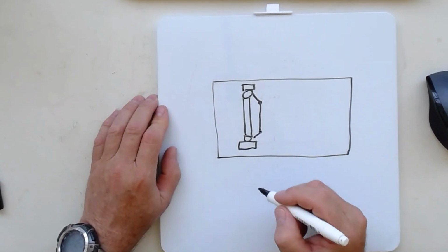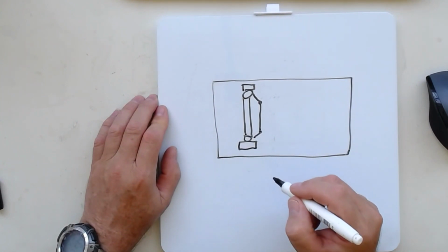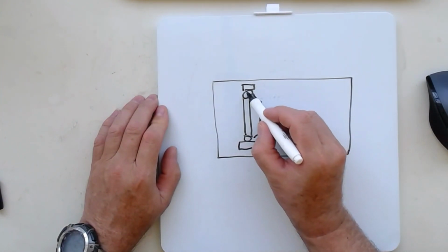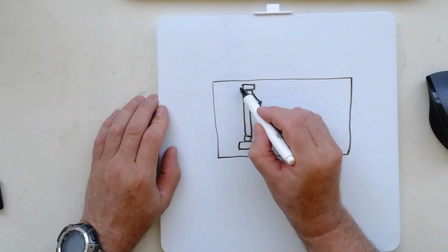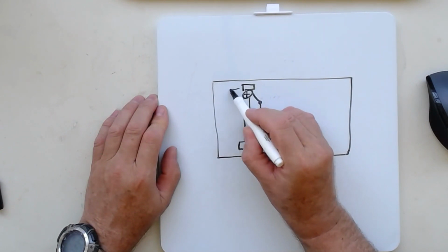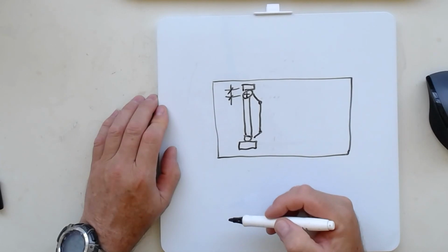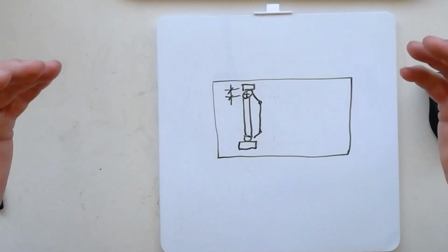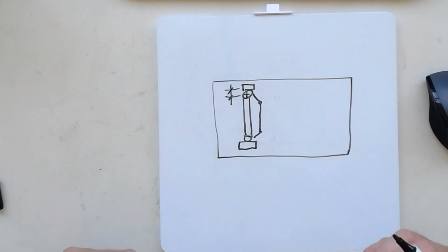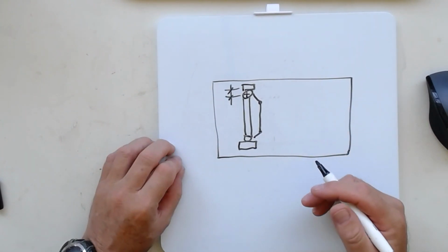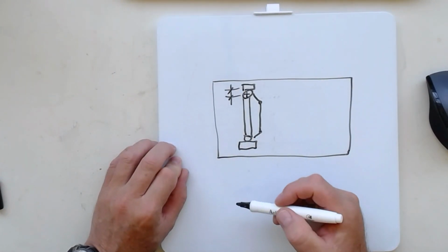Particularly on bigger vehicles, particularly with larger tyres, the distance from the kingpin to the centre of the tyre can be considerable. Now the wheels usually have an offset, so the tyres are brought back into the vehicle, but you still get an offset.